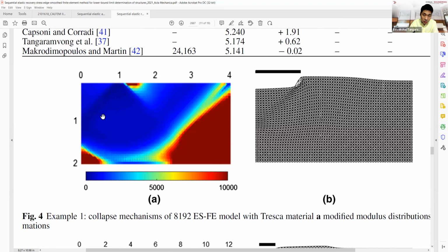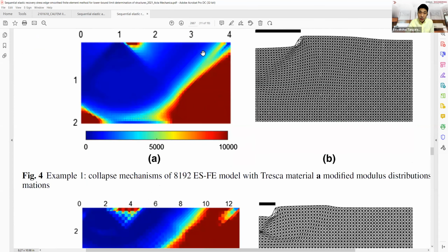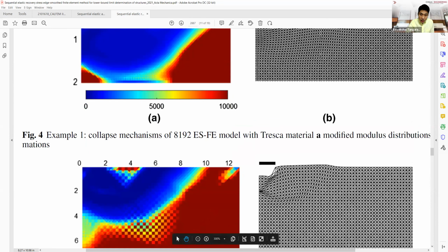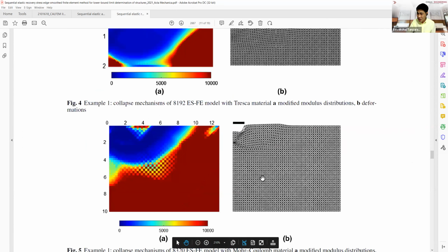When I push the loading, you see that it's deformed. If we push, it has the push-pull effect. We have the push here, and it transfers the stresses to the adjacent area, so that's why it hops up over there. And the stress value has been shown, right? I clamp it, so I fix the boundary. You see that the boundary doesn't move at all. I define the boundary at the center, and it doesn't allow translation in the x-axis. So the more we discretize the element, of course, you have a better idea and the stress starts to converge. But when we check the convergence, right?